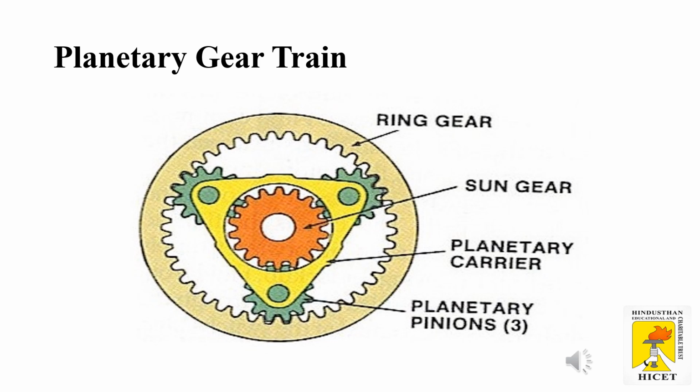Epicyclic gear trains can be subdivided into two classes: one is simple epicyclic gear trains, another one is compound epicyclic gear trains. In planetary gear trains, when there is only one gear on each shaft in an epicyclic gear train, they are called simple epicyclic gear trains or simple planetary gear trains. The main elements of the epicyclic gear train are the sun gear, the planet gear, and the arm or the ring gear.